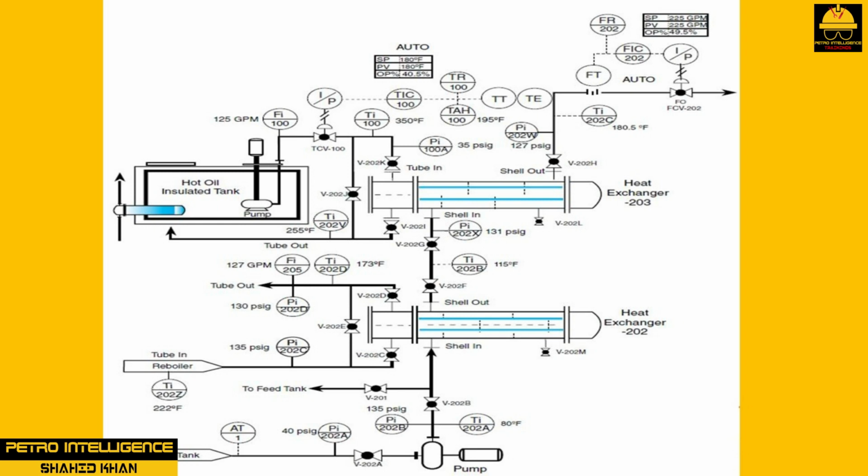2. Ensure all safety hazards are secured: trash, locks, old permits, etc. 3. Check equipment and instrumentation, stroke control valves 0 to 100%, check lineups, etc. 4. Sample feedstock. 5. Line up feed tank to heat exchangers. Check each valve lineup.